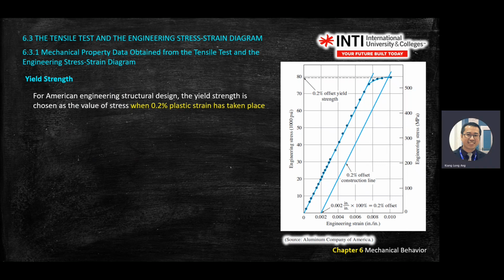There will be one point that is overlapping. There's one value between the new line and the 0.2% offset where the experiment and the calculation overlap or are almost near. Here, you look at the table. There's one value that is very, very near. So this is how you do it. I did tell you how to do it, so after the experiment, I expect you know how.